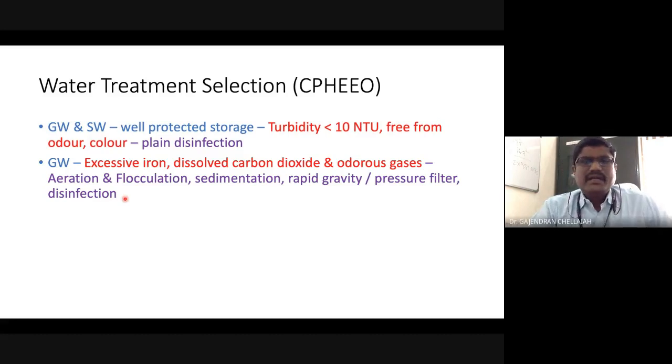Okay, so they are recommending certain norms for design. Suppose you are asked to design some water treatment system, then you're supposed to follow this manual only, the CPHEEO manual. They are giving for both water and wastewater treatment. They are giving what should be your recommendation level for different water quality after treatment for different purposes. Everything is discussed. Even a design example is also given.